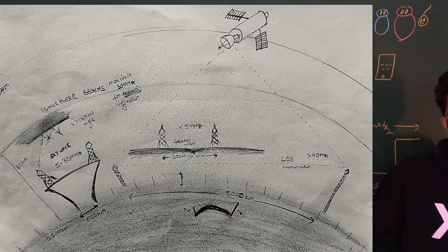Obviously, if you go up, your atmosphere decreases, so you are going from a denser medium to a lighter medium, and when you go from denser medium to lighter medium, total internal reflection is possible. So it is generally sent at a desired angle, such that the angle is greater than the critical angle. So for that, the maximum of the rays can get reflected and can be converged to a tower which is 500 kilometers from your range. That is your sky wave.